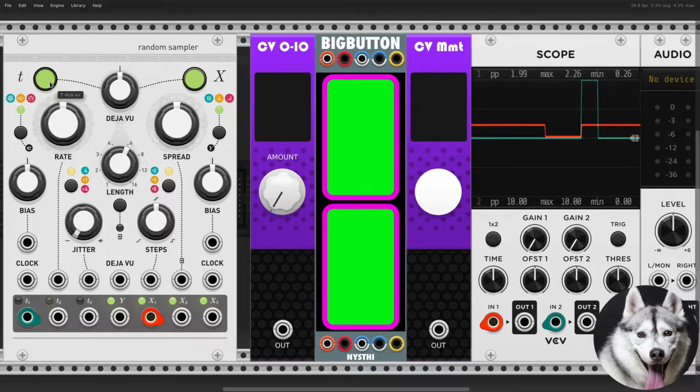One thing that I love about Mutable Instruments, or Audible Instruments in this case, is that the knobs don't have a uniform behavior. In this case, the knob position from 7 o'clock to 12 o'clock results in completely random or a fixed loop, respectively. From 12 o'clock to 5 o'clock, the loop will be fixed, but the resulting sequence will jump within the loop, so we can have permutations of the same sequence.